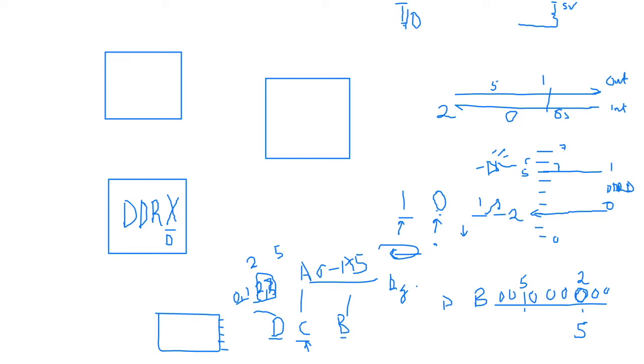I appreciate that. So basically, if we look at the registers, the data direction register just sets the direction. And then we have the port. The port is capital actually, so just make this caps. So PORT X, and we are interested in PORT D now because that's the only one we are connected to. Remember, if we were making use of the analog, this would be C, and that would be C as well.